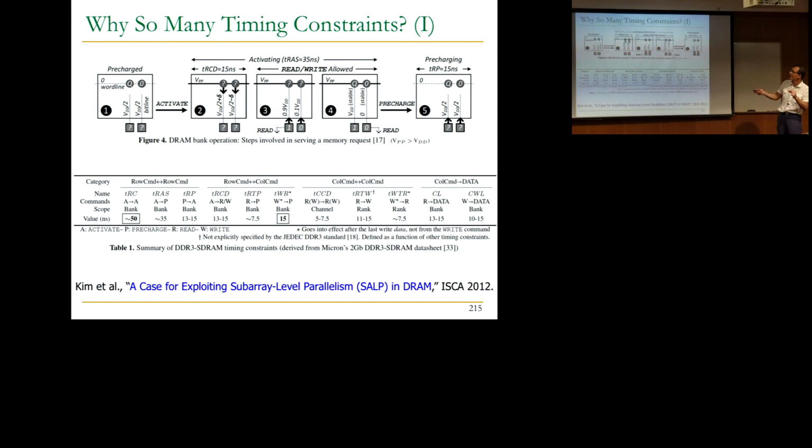So you perturb the bit line by just a little amount. And the sense amplifier captures that perturbation and starts sensing and amplifying the data. It basically senses whatever value that you have on these bit lines. So at this point, the sense amplifier knows that this is 1, this is 0, because this cell over here perturbed this up, and this cell over here perturbed this down. As a result, you got about 0.9 VDD over here and 0.1 VDD over here, and you started with a pre-charge state VDD over 2, which is the middle of the margin that you have, 0 to VDD.